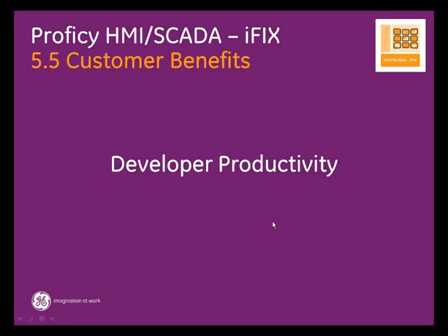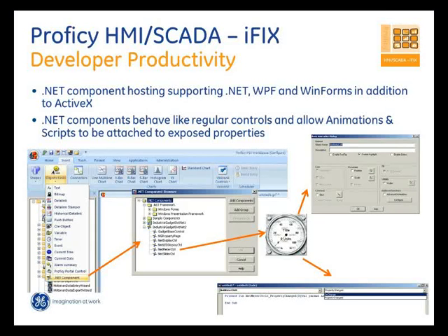So going into the developer productivity aspect of iFIX 5.5, the first capability that we enabled in iFIX 5.5 was the ability to now host .NET or WPF or WinForms objects into an iFIX graphic. Earlier, prior to 5.5, anyone who had a .NET object or had developed a WPF object had to do further work in wrapping that object up into ActiveX.